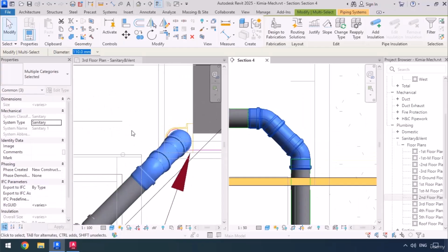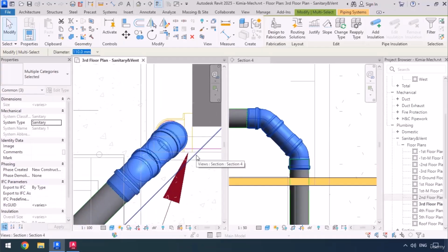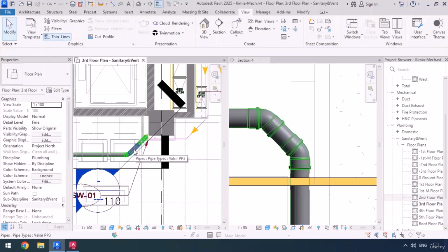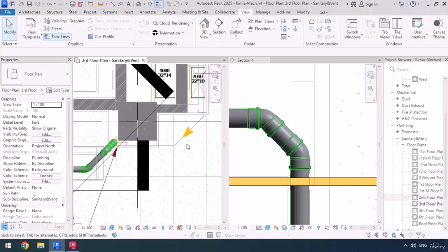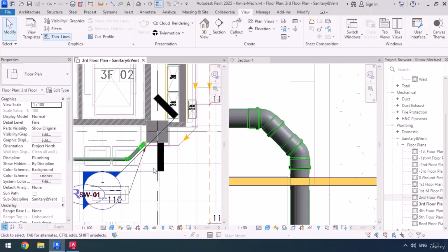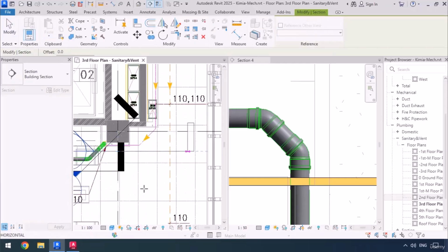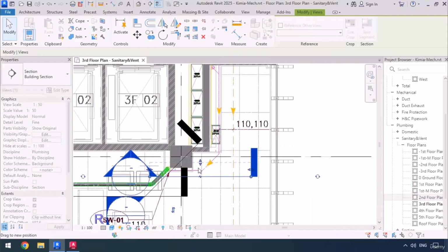Now also in the floor plan I'm going to move it to the left, and then I'm going to stop at this point. Now it's by the column's corner cover. Okay, so after this point we're going to have to draw a branch for the riser number 1 to connect to it. First I'm going to create a section here, click, and click. Then I'm going to also close this section, and make sure to make this one a little tighter.